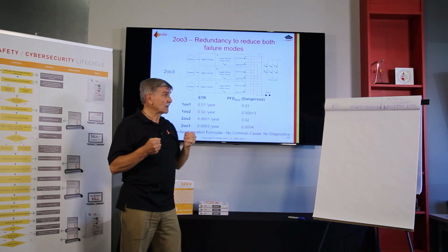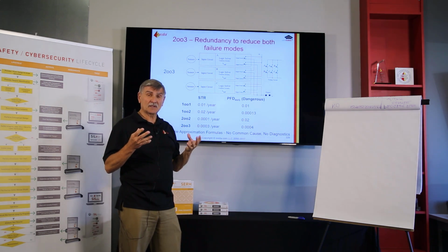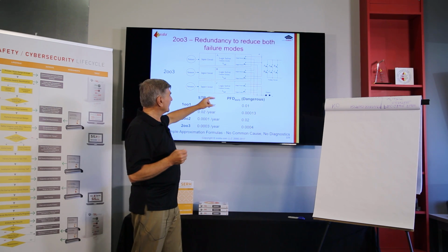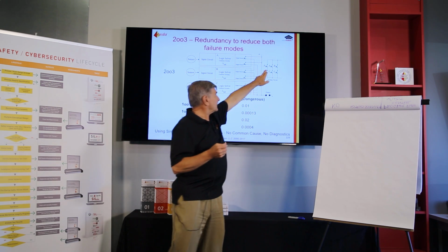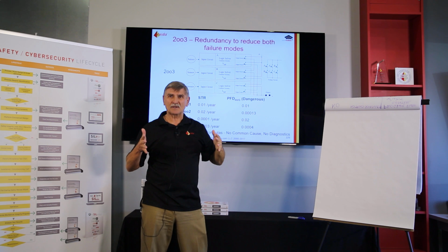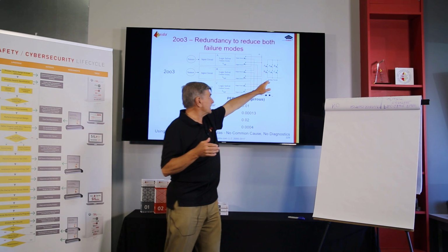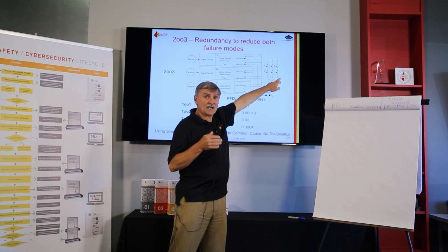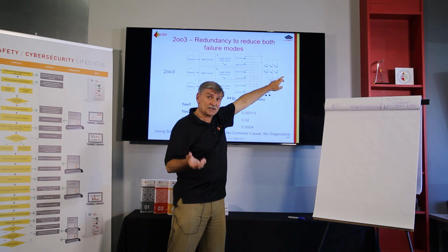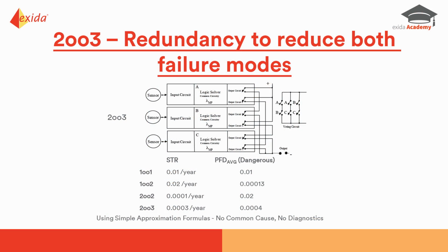What if one fails safe? Okay, let's stick with A. The A switch is open circuit. Does the final element remain energized? Yes. Why? Because B and C continue to supply power to the final element.